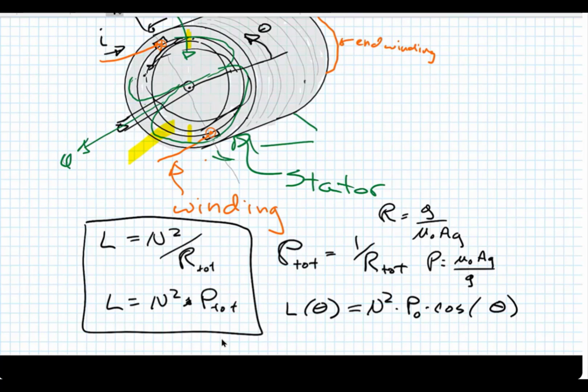Passing by a specific point on the stator, for example, being observed, it's going to see a small gap and a big gap and a small gap. How many times do you think it's going to see a variation there? Once or twice? We'll see it twice. Right, 2 times.